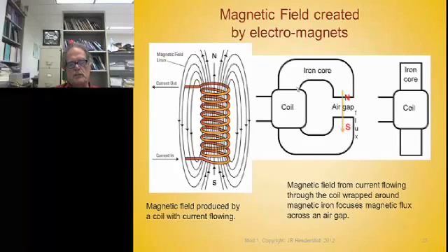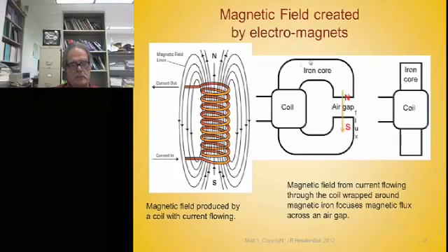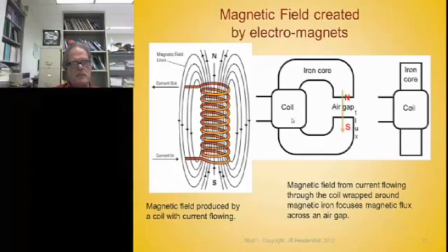But if you use the very pure Swedish iron with no impurities in it at all, it's just pure iron, then you get permeabilities up to 6,000. So those kind of materials are very happy to collect all of this flux. There's our coil. We've shortened it a bit. We wound it so all the wires are bunched together.